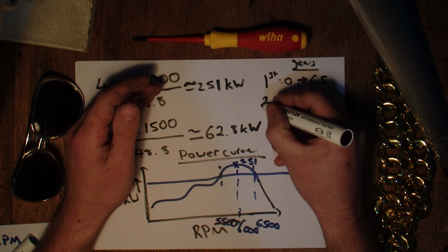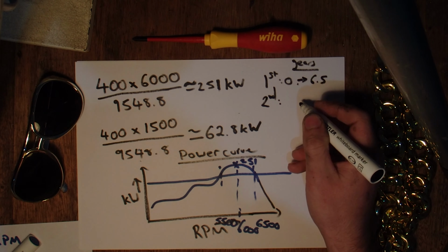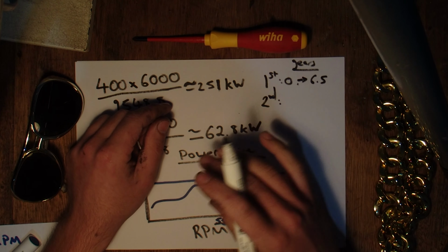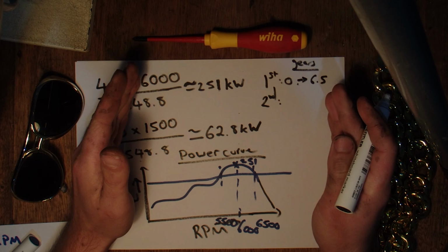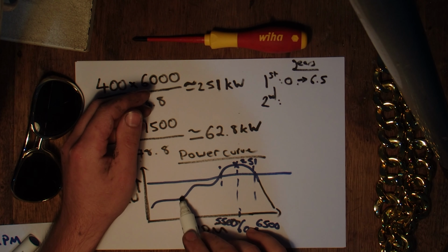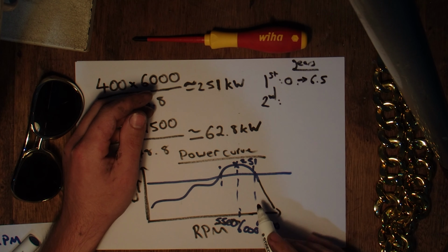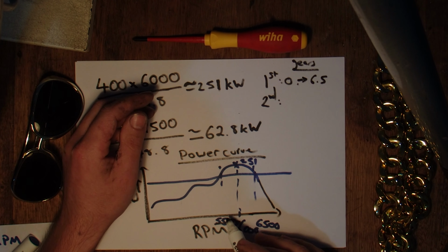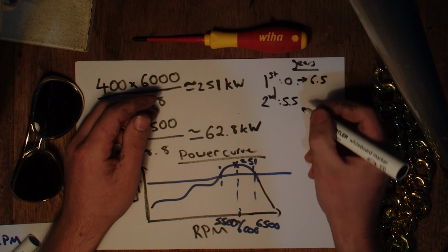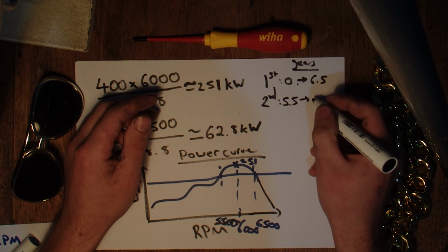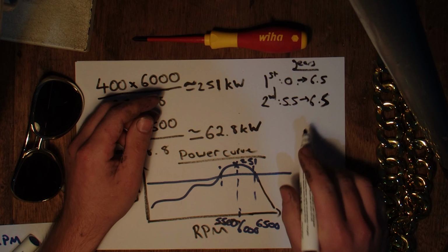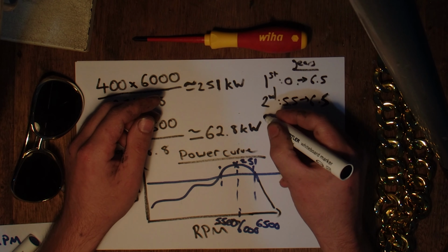And then we're into second gear. If we had unlimited choice and we wanted to select a gearbox and we could pick every single ratio so that everything would be perfect, in a perfect world, we wouldn't be coming back to 3,000 RPM because we've got no power there. It feels like the car's bogging down. So we'd try to get a gear that would shift us back to 5.5. This is perfect world stuff. We want to go from 5.5 back up to 6.5. Bingo, bango. We're cruising. We're changing gears. Bang, back to 6.5.